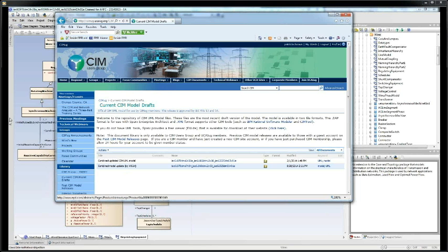If you look at the transformer model, let's say just take the tap ratio model, you can actually have several transformers using the same regulation schedule, and you have the capability of deselecting the control at the regulation schedule level or at the individual tap changer level. So you can actually turn a tap changer on or off.